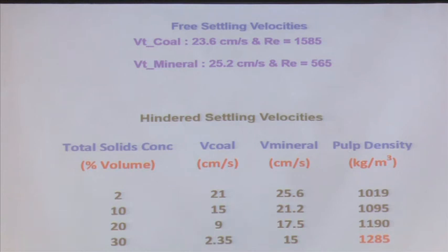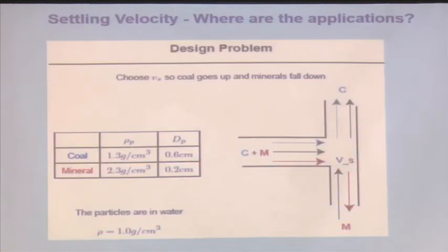That also I have to check, because if my slurry density is very high and approaching the density range of the particle, then my mineral particles will have difficulty in settling. So, I have to look at those conditions also.